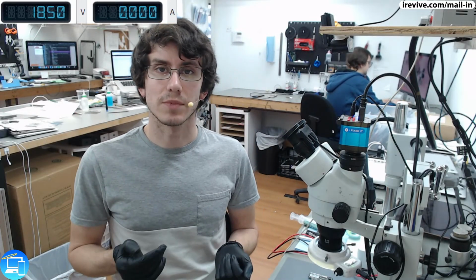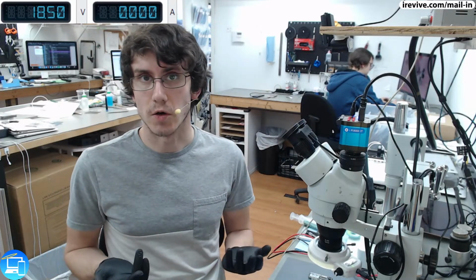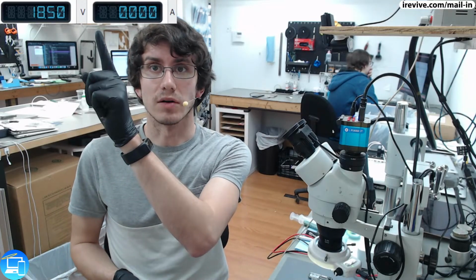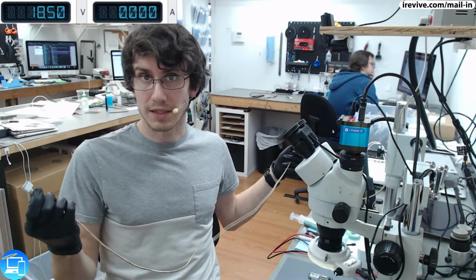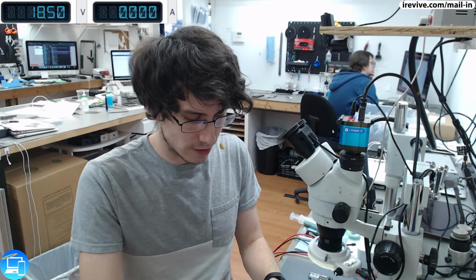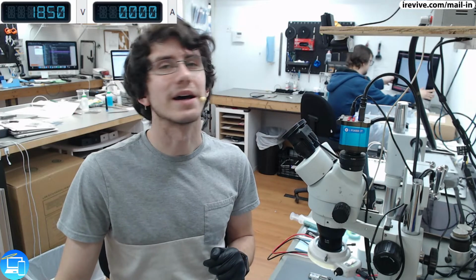820-00165. This MacBook's in here because it just isn't turning on. Customer went to go use it one day and has no signs of life. So I've gone ahead and hooked up my voltage and amperage meter here, our power supply, and we're going to check and see how much amperage we are drawing. So whenever I connect the logic board here, we are currently not reading anything. Why is that?